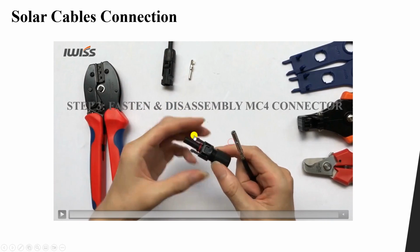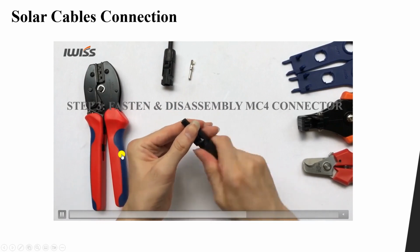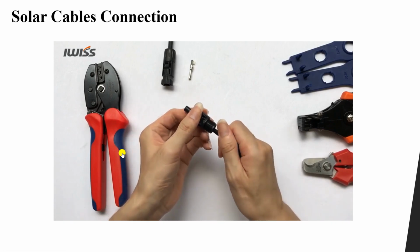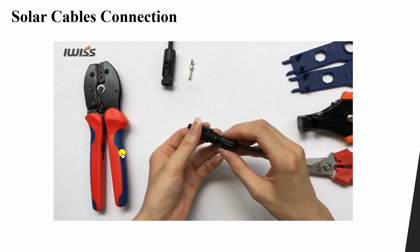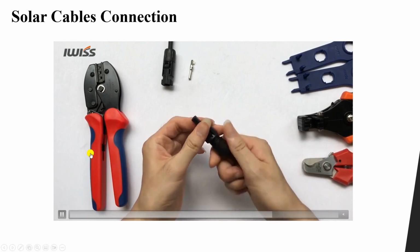Now I'm going to add it to the MC4 male and female like this. Put it like this, then remove this one, rotate and remove, then put it inside like this, then rotate again like this, keep rotating.